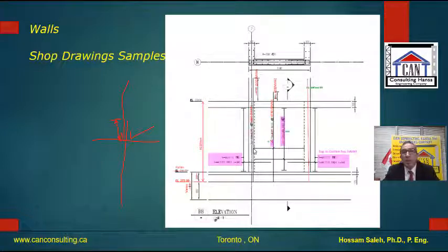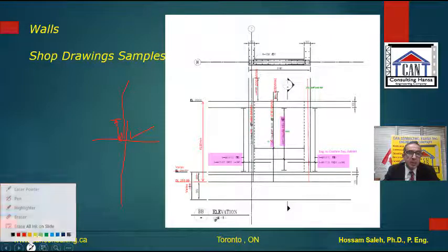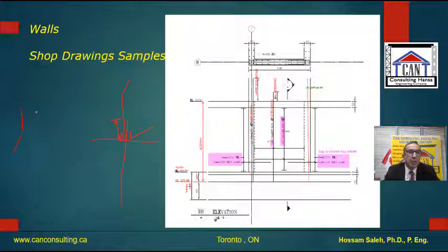It should be 20 spacings, and 20 spacings will mean 21 bars. So if we say here is 400, 200 and 200, so 400 spacing, so 2 times 200, but 3 bars. So the number of bars is always one more. So in the construction industry, they sometimes miss 1 bar by mistake, and sometimes also the overlapping length is not clear for them.